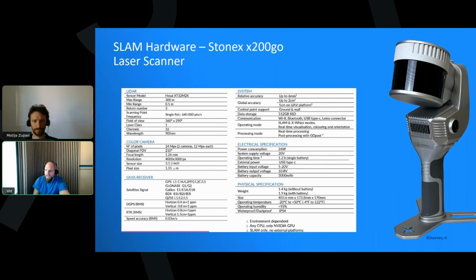The sellers told us that when you do the scanning, 50% of the time you should have RTK. If you want high absolute accuracy, you can move inside, and after the inside scan you go outside again and walk outside, so you don't have a blind polygon but have georeference information. For a while you rely on SLAM only, and then you go back out to get the georeferencing running again. So you should also close the loop? Yes, basically. You don't need to place the scanner on the same point again, but you can move outside and walk over the same area to increase the accuracy a little bit.